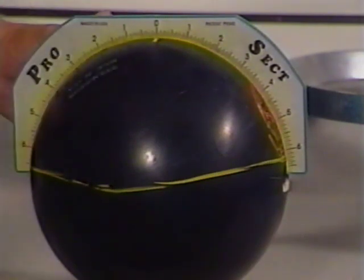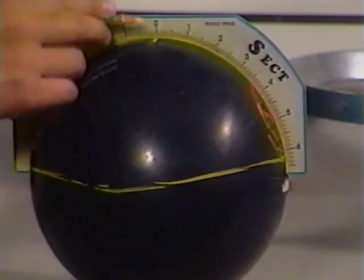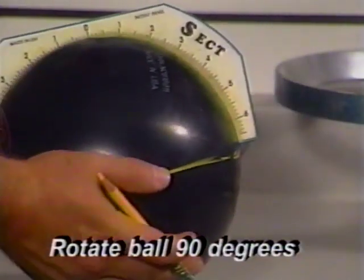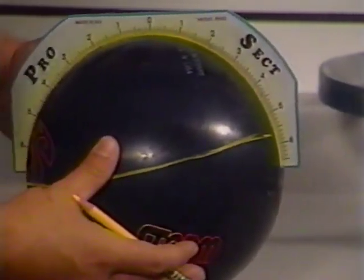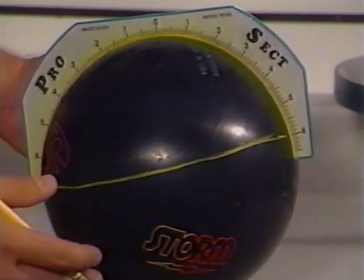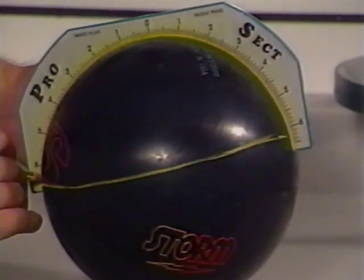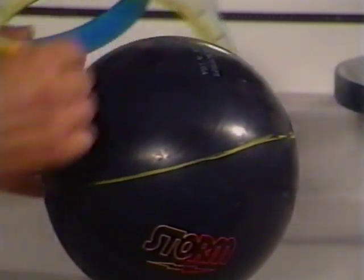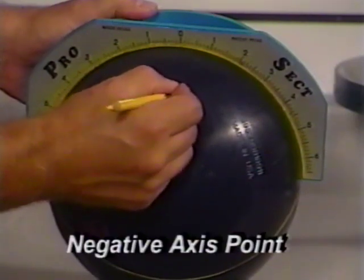Be sure at this point not to drag the pencil with the quarter scale, but go against the 0. Now I just want to turn the ball 90 degrees. Doesn't matter if I'm exactly 90 degrees, but again I will look for the points that intersect my quarter scale in the same area. Now we have 6 1/4 on this side, 6 1/4 on this side. Again, I will make my slash at the 0. The point where my 2 slashes cross is the negative axis point.